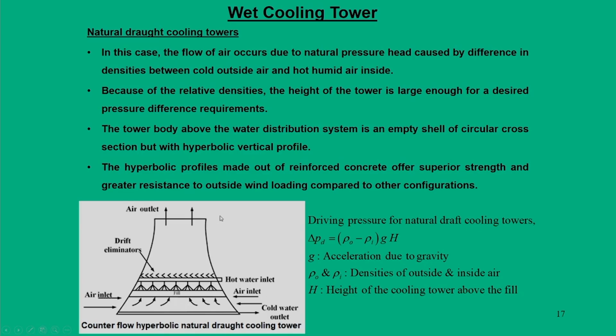So, driving pressure becomes the density difference times g times H. So, essentially the height H is nothing but the height which is just above this fill. Of course, this is the empty space, but this empty space is required to maintain this density difference. In that way, we take the advantage of the atmospheric air and the air inside this cooling tower to create this density difference.